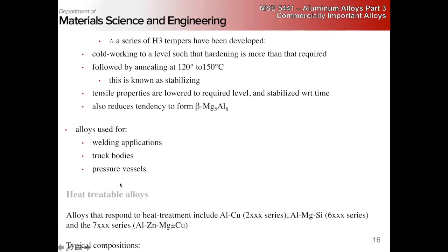So the heat-treatable alloys, right, are the ones that we typically think of when we rely on precipitation strength. Right, the non-heat treatable alloys, I still talked about precipitates a little bit, but it wasn't the primary means of getting strength. We typically use these in H tempers, hardened tempers rather than T tempers or heat-treated tempers.